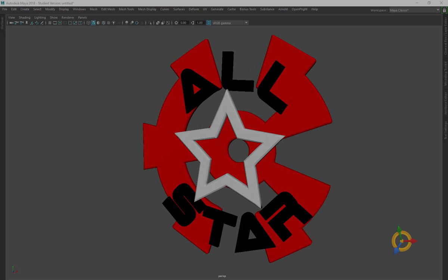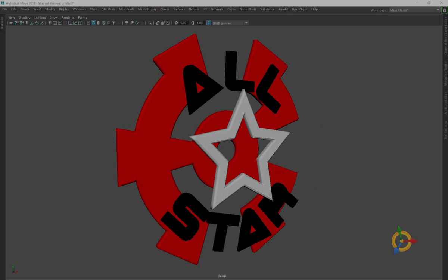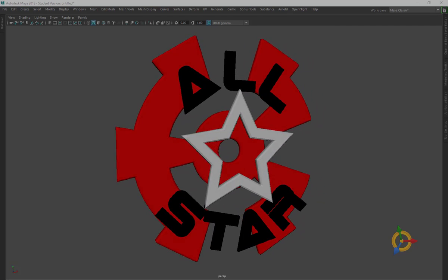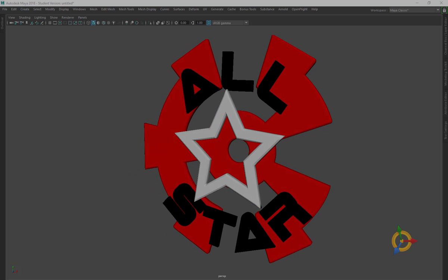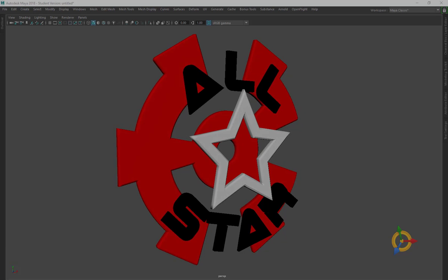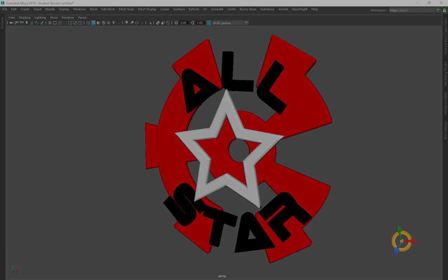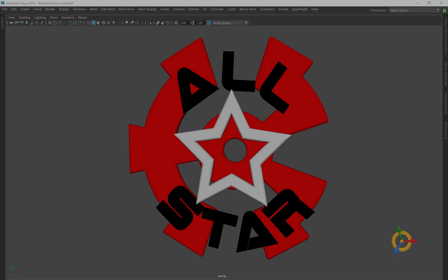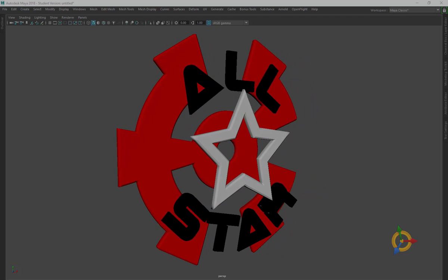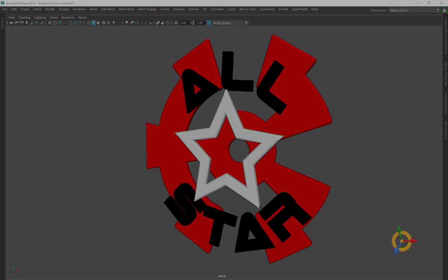So we can also do this with things like AutoCAD drawing files, .dwg files. So we could take the plan of a building, for example, import those files into Maya, and then extrude the shapes using the vector information within those files. So you can actually produce 3D models of buildings by extruding out these two-dimensional files.